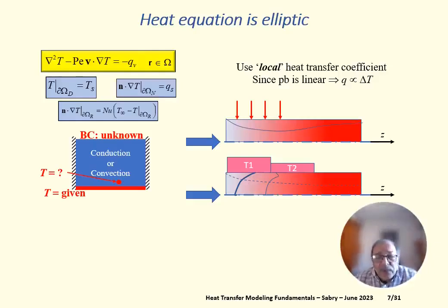And then we will have the following peculiar situation in which, although the wall temperature is higher than the bulk temperature, heat will flow, in fact, from the fluid to the walls, because it will flow from the thin hot layer just next to the walls to the walls. In this case, if I'm still blindly assuming that the relation between delta T and Q is local, then I will have to define a negative heat transfer coefficient, for instance. It's completely silly. It contradicts the second law, and the problem is not in the second law.